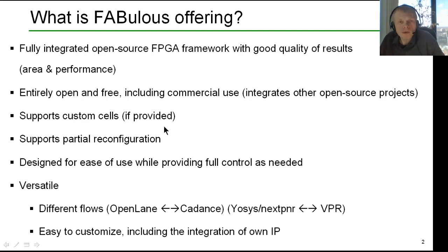It supports partial reconfiguration, something that's very useful for embedded FPGAs, but that you don't even get from a lot of industry offerings. It's designed for ease of use, while it provides you full control over all aspects of the flow whenever it's needed. It's versatile in the sense that you can use different flows for the ASIC implementation as well as for the Verilog or VHDL to bitstream compilation. That includes open source tools for all aspects of the flow, but also industry tools like Cadence, for example for the ASIC implementation.